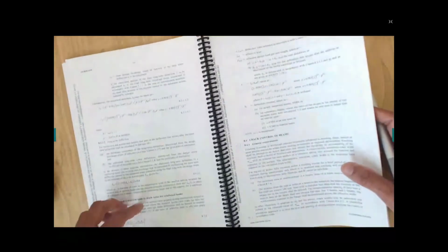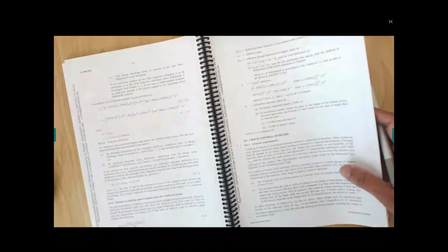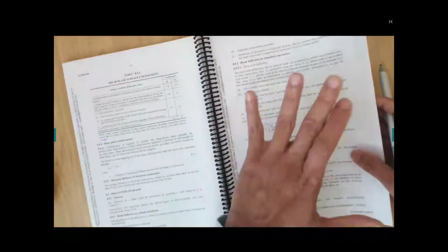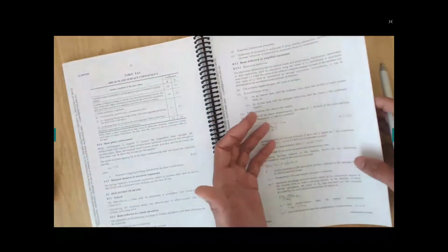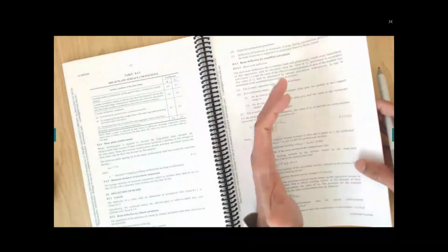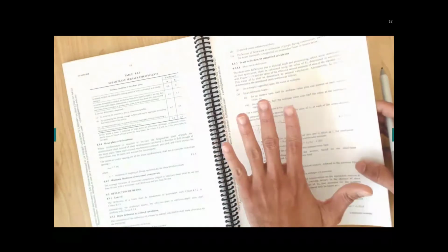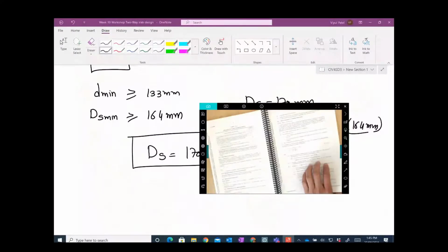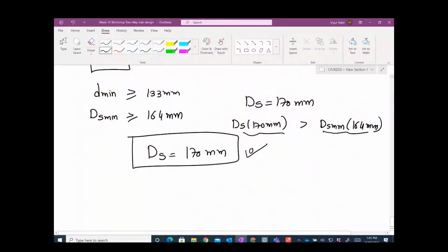We used this one and found about 170, about 153 millimeters. That's fine. Look, if you want to calculate more accurately, the refined calculation would be the more accurate one. If you go through this again with an Excel sheet, I am sure you might be able to reduce that depth to 150 millimeters. We have done the calculation in the background, so we know this depth can be further reduced and should be okay. In your tests or exams, if you continue with 170 millimeters, that is okay. There is no reduction of marks or anything. 170 millimeters is okay.